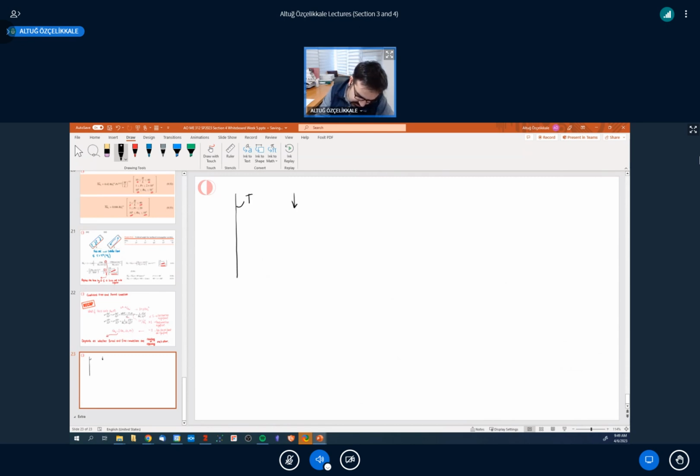The surface temperature is greater than T infinity. Therefore, as natural convection, you are going to obtain a net flow in that direction with our velocity scale u0, so I will indicate free convection by this velocity scale u0. On top of that, if you introduce a forced convection with a free stream velocity u infinity, what you are talking about is, in essence, an assisting configuration. Forced convection is assisting free convection, or vice versa.